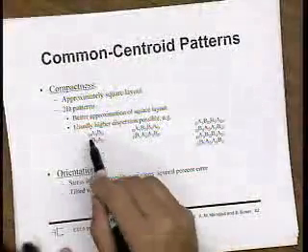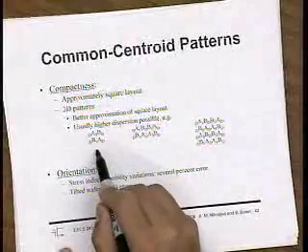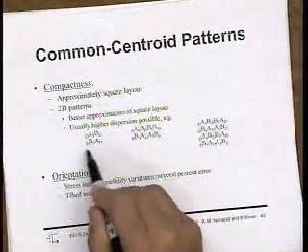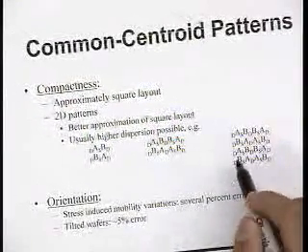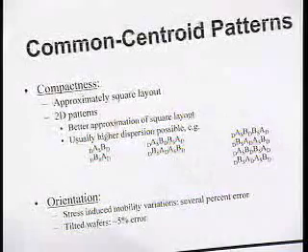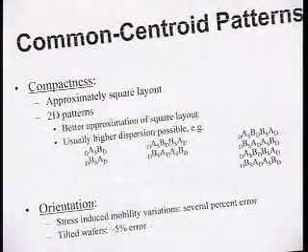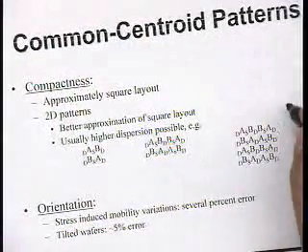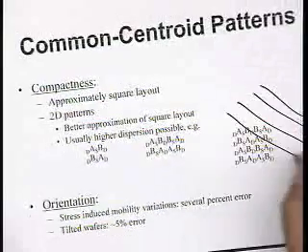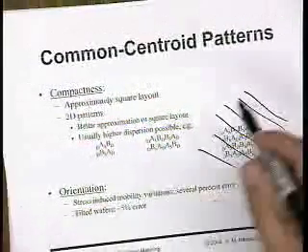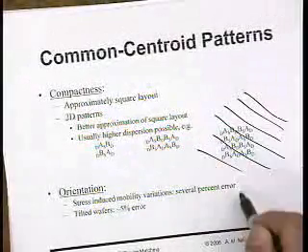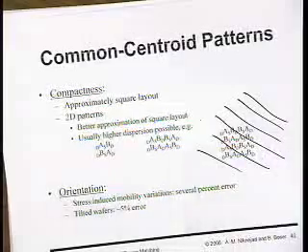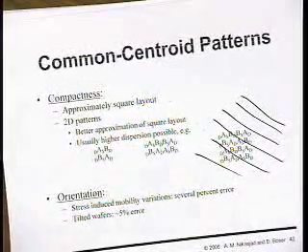So here's a little bit more detail. This is the drain, the source, the drain, in a multi-finger layout device. So this is our standard common centroid layout. As we divide it up into more and more unit elements, we can do something like this and maximize the amount of intermingling we have. And at the end of the day, what we're doing is we're fighting linear gradients. You can sit down with this and play with it and show that no matter which direction the gradient flows in, this will combat it as long as it's a linear gradient.